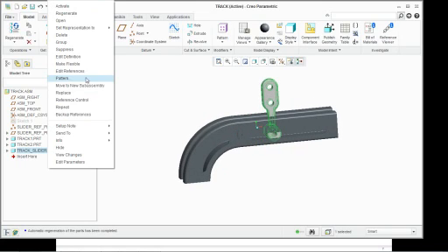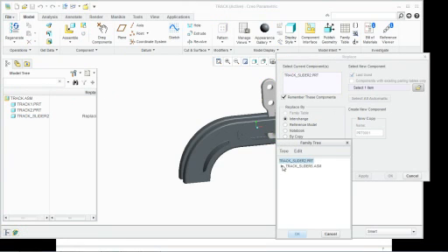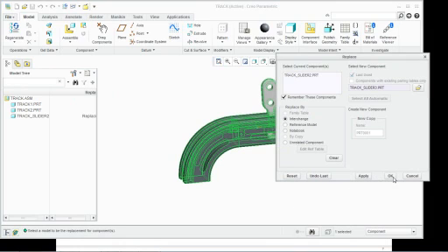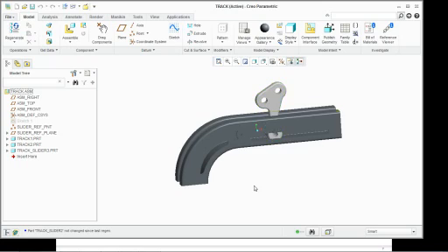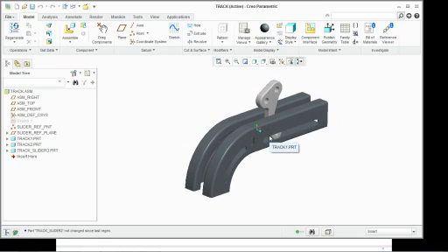I can go in and simply replace using an interchange again, click open, and this time pick maybe that track slider 3 and click OK again. And when I click OK, notice now it's changed to that other kind. Well, that's fine and dandy. Do I have to go back and make a new interchange every time I add an assembly, delete them all off and add new ones? No, it's really quick and easy to go in and add new parts to an existing interchange.